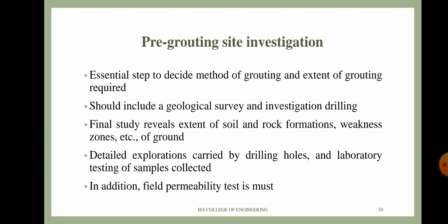Detailed explorations are carried out by drilling boreholes and collecting samples from the drilled boreholes for laboratory tests. In addition to all these steps, a field permeability test must be conducted to facilitate more precise estimation of the required pumping pressures, grouting pattern, and type of grout.